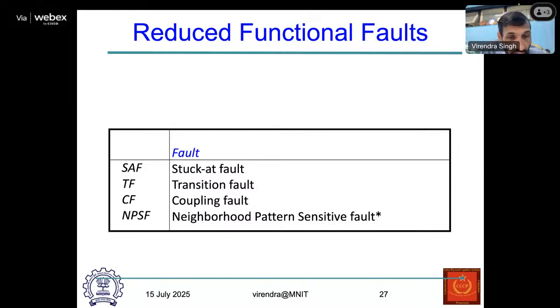And that's where this n square and n log and all those complexities start to come into picture. Because here if I say coupling, one cell can be coupled with any other cell in the circuit. In that case, in order to test that particular fault in a cell, I need to change the value in all other cells and see what is the impact on this particular cell, right?